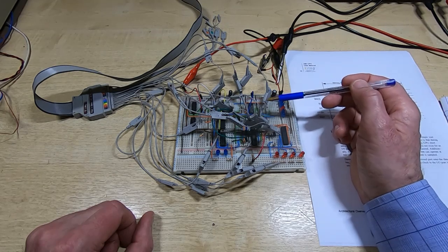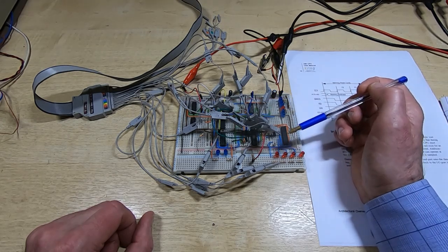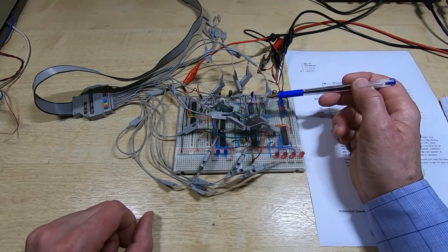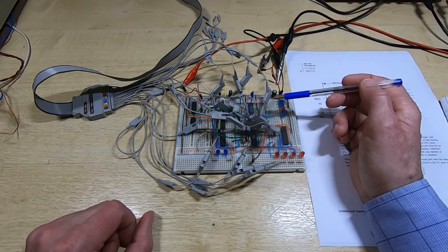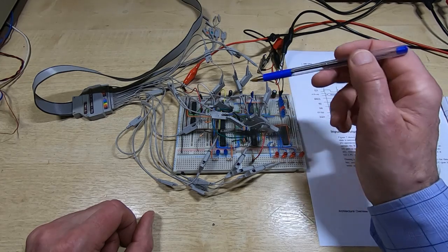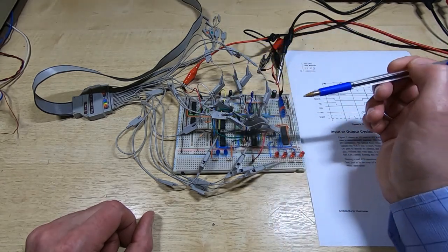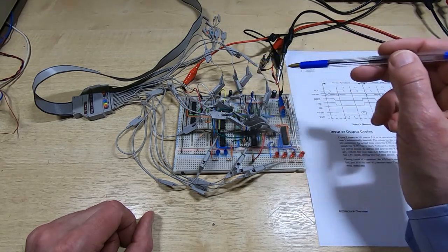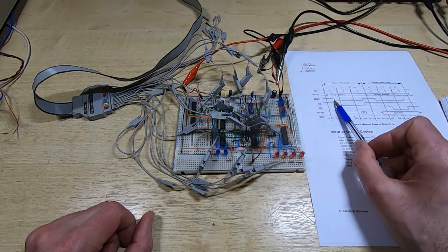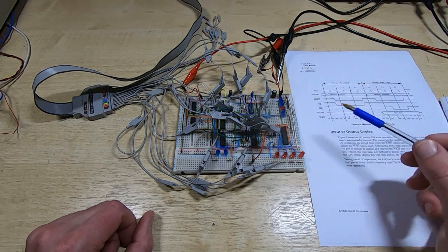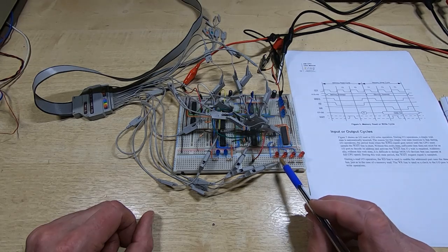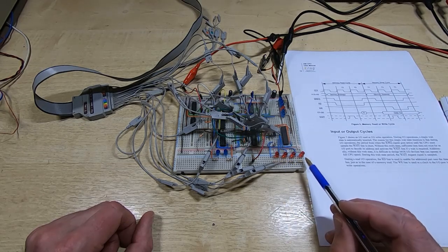So the Z80 will at some point give us access to the address and data buses, and it indicates that by lowering the bus acknowledge line. This circuit then will start using the incoming clock signal to go through the various steps required to generate these signals. So the signals going out are indicated down here on these four LEDs.